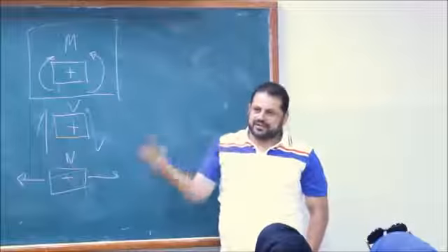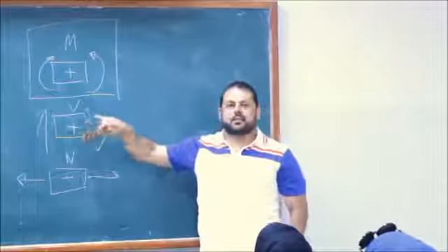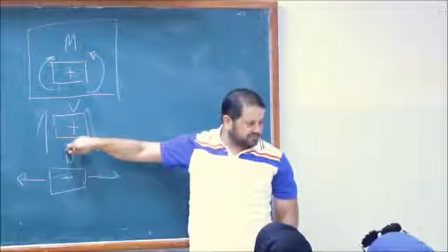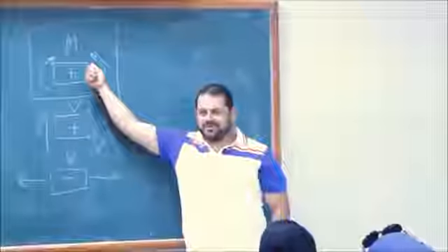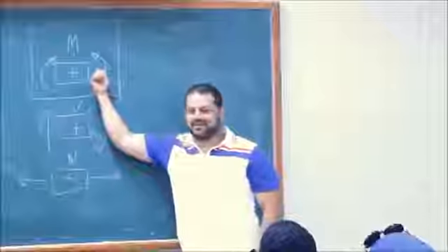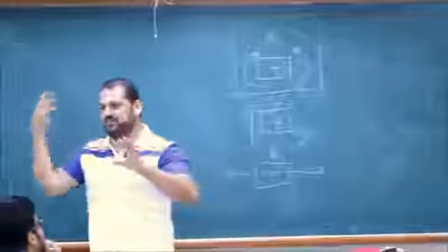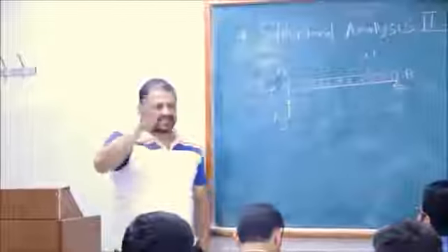So if both give me tensile stress. Why is it important to know whether this is a positive shear or negative shear? Because positive shear gives you positive moment. Negative shear gives you negative moment. So when you draw the shear diagram to draw the moment diagram, if it's positive, it means positive. Okay? Now, we're going to draw on the right side.